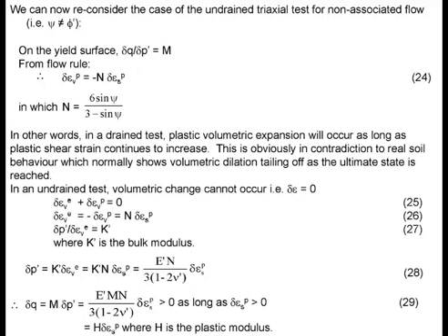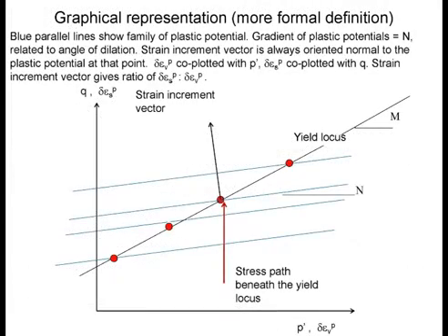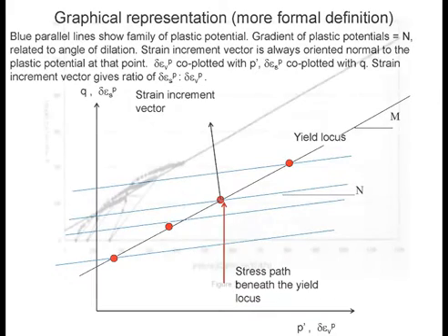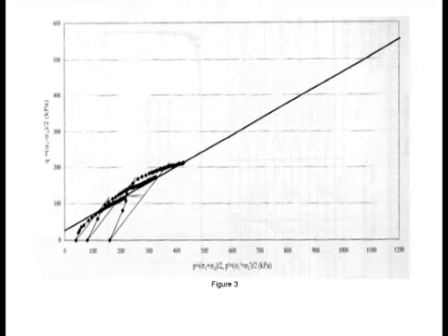Now, the question then is, what happens if it is a drained situation? This is another question in your assignment. Basically, the undrained stress path in an elastic material is always vertical. Now, when it hits yielding, it starts to go all over the shop. And you can see the stress path following the U locus. This is not totally unrealistic because in an undrained situation, I'll show you the other stress.